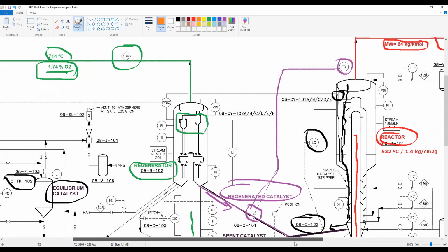But you have to ensure here that you will not have particles of catalyst, and also in the reactor, that we don't see it, there is another disengager here when you finish the riser. There is another mechanical piece that will make the first separation of the catalyst from the vapors. Of course we cannot see all the details here, but we have some disengager that makes a first separation of the catalyst and the vapors, and then you will have the cyclones.